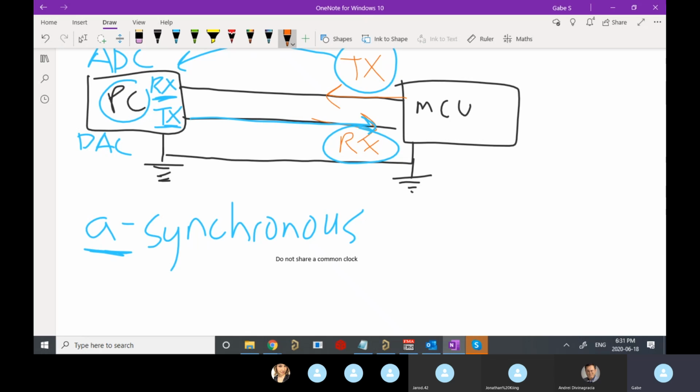And we agree on a speed beforehand, and we call that the baud rate, right? Sometimes people refer to that as the speed. If I'm sending you zeros and ones at 2 times the speed you expect to receive them, you're only going to get every second one, right? And so the microcontroller needs to agree on a certain baud rate. So one very common one is 9600.